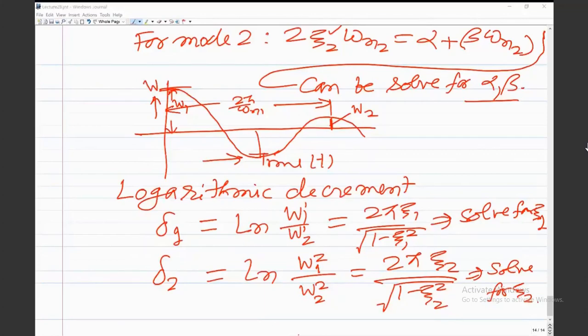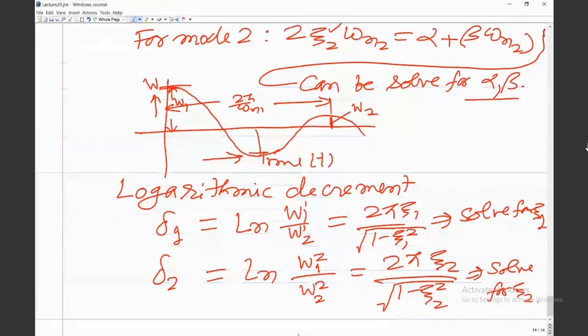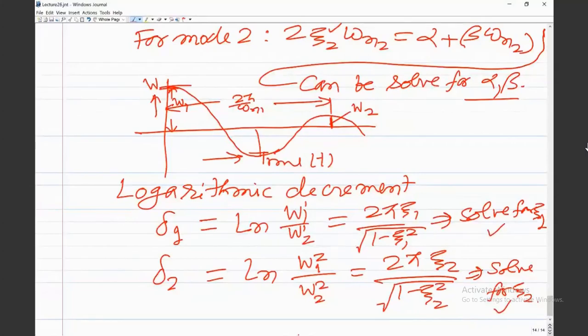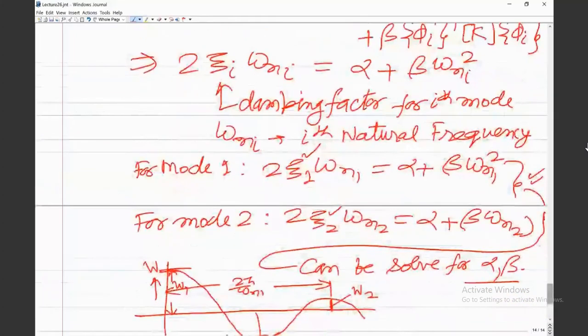Now if you look at the damping here, we are determining the damping based on just two modes, the damping factor in just two modes. So if the force is a function of time and it is exciting different modes, and the modes which are excited are different from the modes which are used to find alpha and beta, that is xi1 and xi2, then the damping will not be that accurate. But still, usually, what is the observation